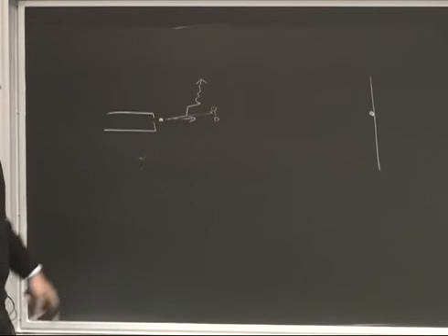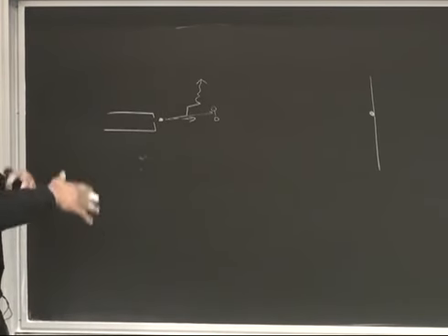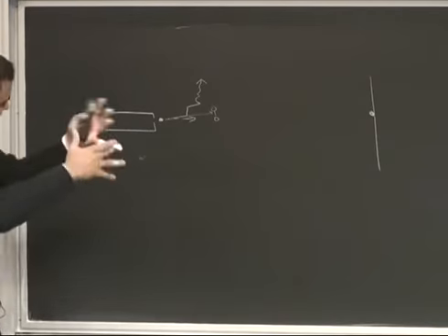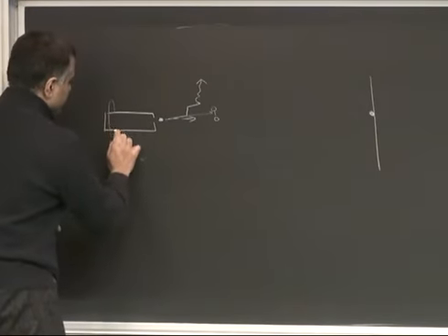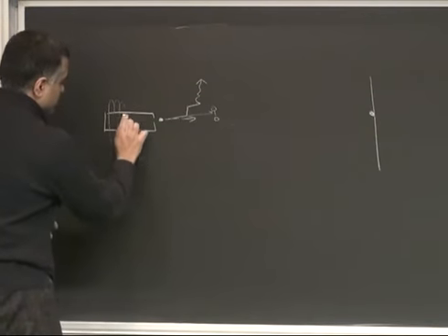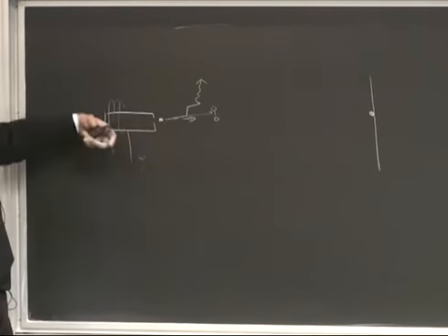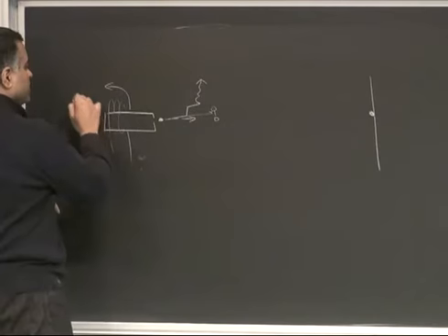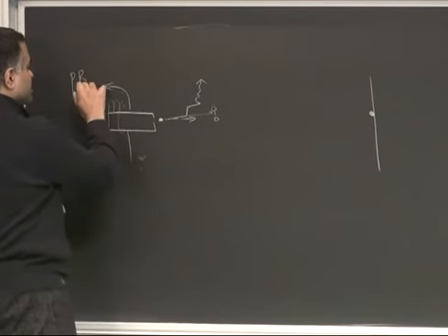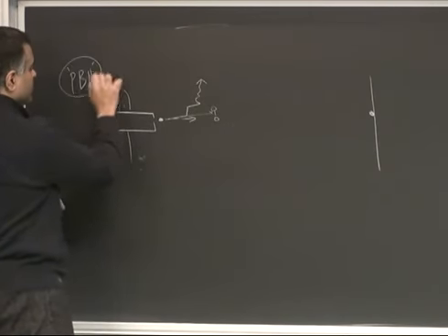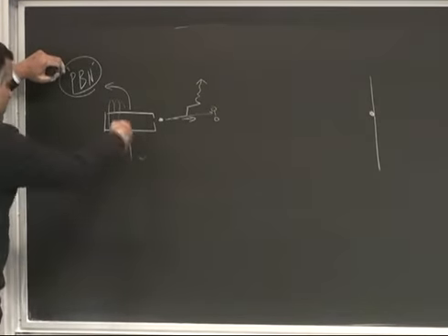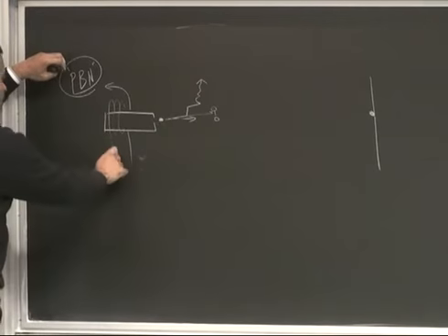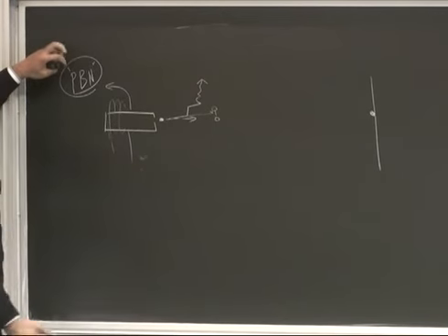Let's just briefly discuss that. As I said earlier, I'll discuss this in greater detail later. Typically, for some solids, you would have a crucible, a high temperature compatible crucible. What's used is pyrolytic boron nitride, PBN, and then you wrap a wire around it and pass a lot of current through it.